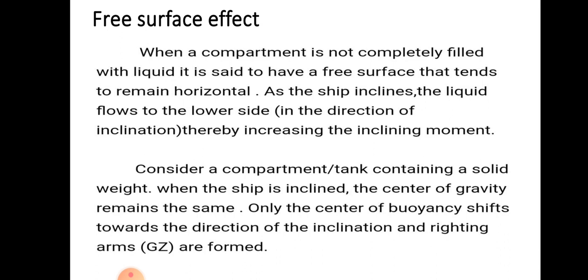Consider a compartment or tank containing a solid weight. When the ship is inclined, the center of gravity remains the same. Only the center of buoyancy shifts towards the direction of inclination, and the righting arms are formed.